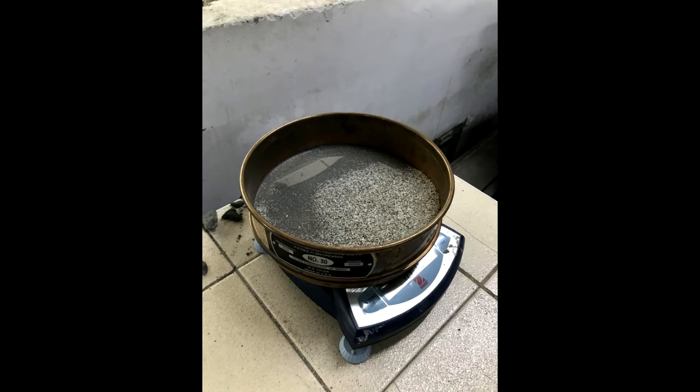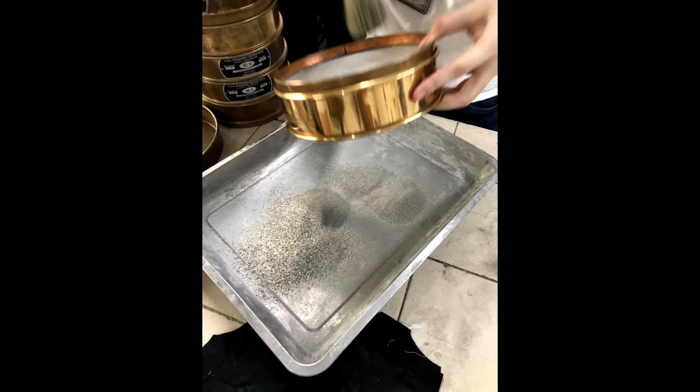Considerations: 1. Make sure the sieves are in the proper order. 2. After using the mechanical shaker, the process of manually shaking the sieves is very important. This is to make sure the samples are thoroughly sieved. 3. The weight of each sieve should be taken to obtain the amount retained in order to calculate the cumulative retained and also the percent passing for each sieve.